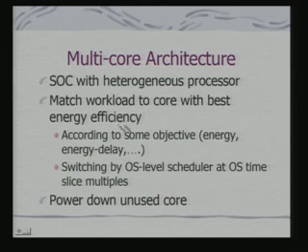From the point of view of energy consumption. So, it can be according to some objective of energy consumption or even the energy delay product, which looks at both the parameters together. And this switching here is done by the OS level scheduler at OS time slice multiples.